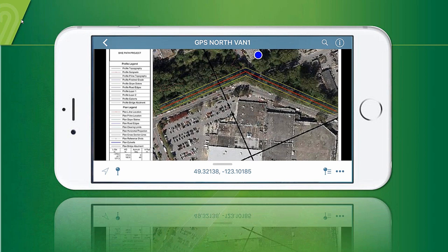I just make a comment there, Aaron. When you exported it, it warned you that the plan view was rotated. It still works fine, but the reason for the warning is you could have a plan profile sheet, and if the plan view is rotated, it's a little bit confusing when you see your GPS location on the sheet and you read vertically down onto the profile. It's not going to match, if that makes sense. So if you've got a plan profile sheet together, you probably want to keep the orientation of the plan view north-south.